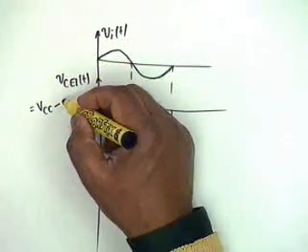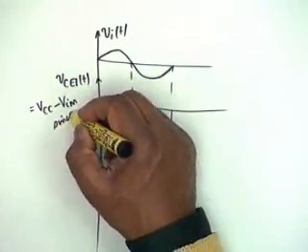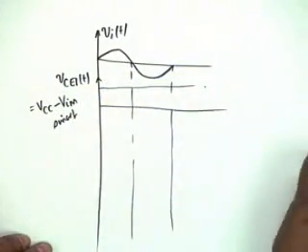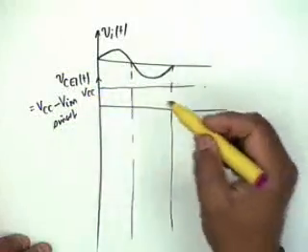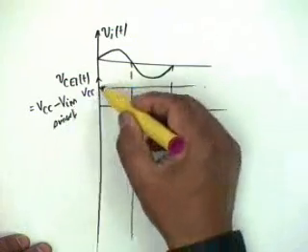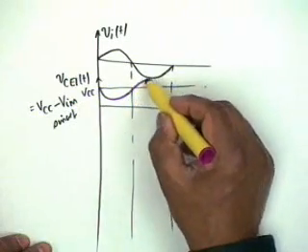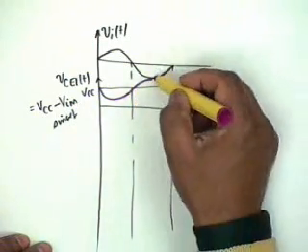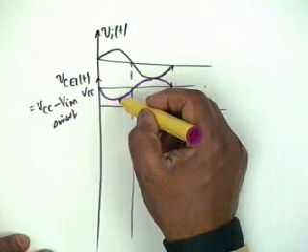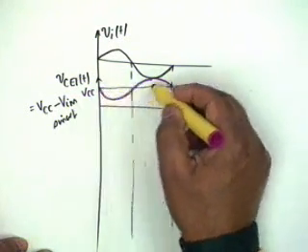So it would be of the form VCC minus, let us say, VIM sin omega t, which means that if this is the level VCC, then to start with it will go negative, agree, and then it will go positive like this. The maximum value here would be VCC plus VIM and the minimum value would be VCC minus VIM. Is the point clear? Okay. It is superimposed on VCC.